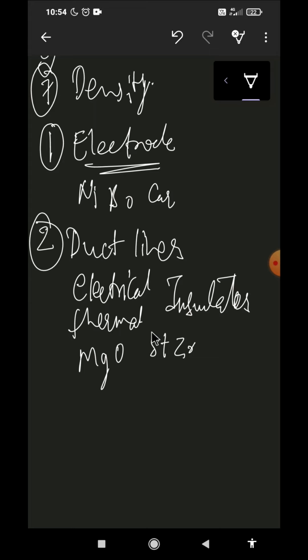MHD ducts have to withstand a temperature in the range of 3000 degrees Celsius. Presently steam cooled walls made of insulated laminations of very thin nickel or stainless steel have been tried. The research is on to use suitable ceramics or coatings of ceramics as duct materials.